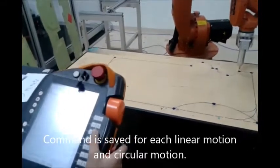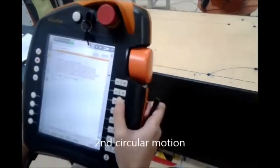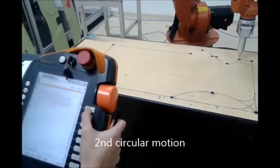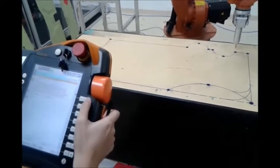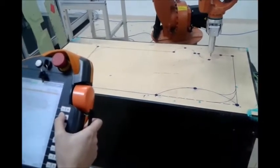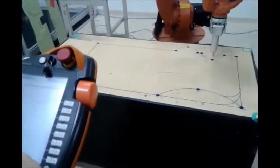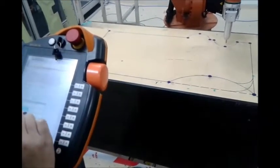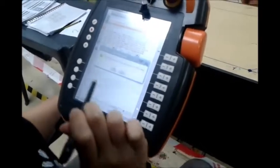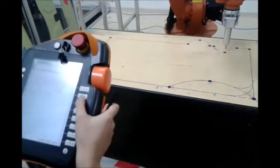Okay. So next I will do circular motion. So I'll proceed to the center point first. So this is the center point, and then click command motion and choose the circular motion, and then teach auxiliary. Yes. Okay. Then I'll proceed to the next point.